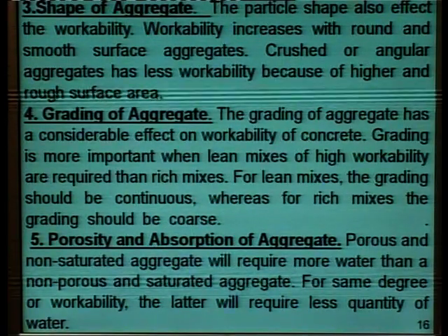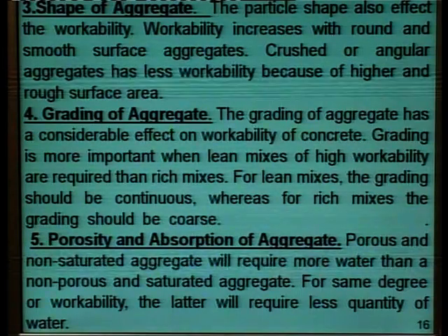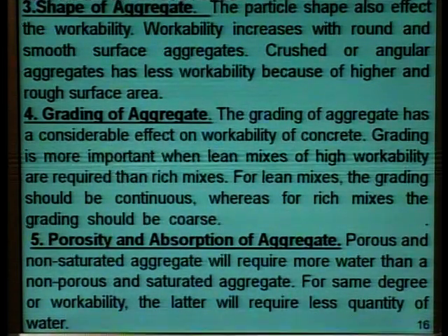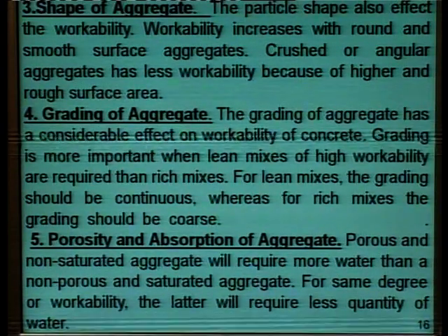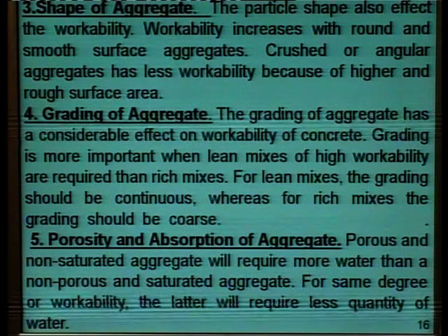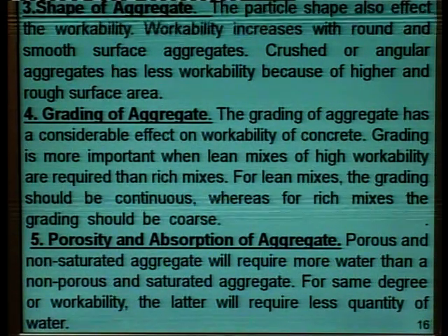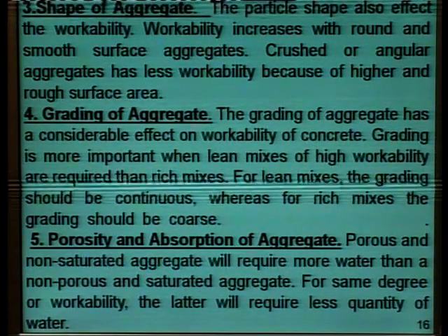Fifth is porosity and absorption of aggregates. Porous and non-saturated aggregate will require more water than a non-porous and saturated aggregate. For the same degree of workability, the latter will require less quantity of water.